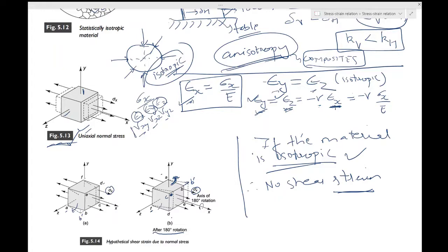The same is happening over here. You cannot have shear strains of opposite senses for the same applied loading, which is the stress over here. So this contradiction is avoided only if the shear strain due to normal stress component vanishes. And a similar argument would show that the other two components of the shear strain vanish. So which was this component, by the way, can you recall? It was on the y plane in the z direction, right? Yes. So it was gamma yz, this particular strain.